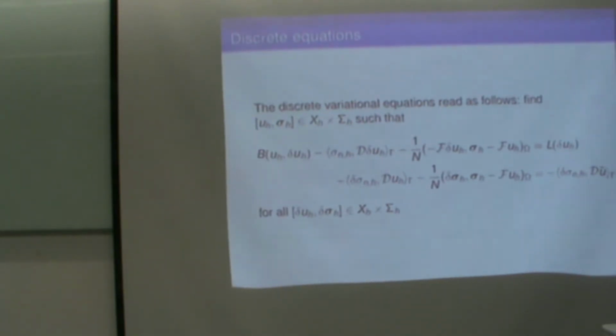And that's important, for example, if you have very anisotropic meshes. That's what we wish to do for flow problems, because we want to deal with boundary layers, which is a hot topic in the case of immersed boundary methods. Okay, that's it. That's the method, essentially.